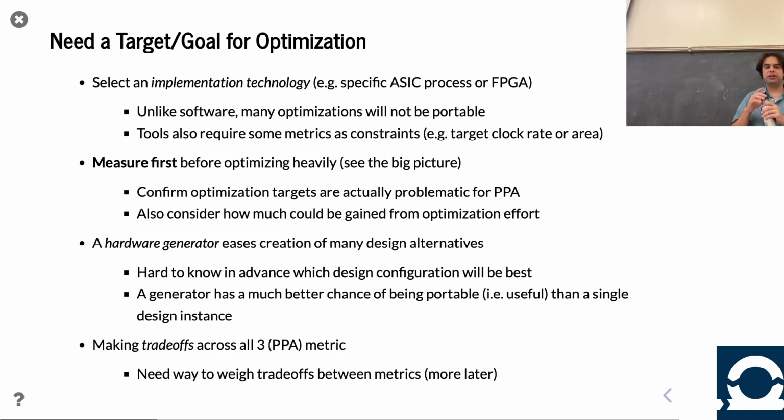Was there a difference between parameters in Chisel versus parameters in Verilog? Good question. In Verilog, or I should say SystemVerilog, you can have numeric parameters, so that's totally doable, and some really clever SystemVerilog implementers can use that. But for some of the things that we do in Chisel and our generators, it's not so much just the parameters, it's how you use those parameters.